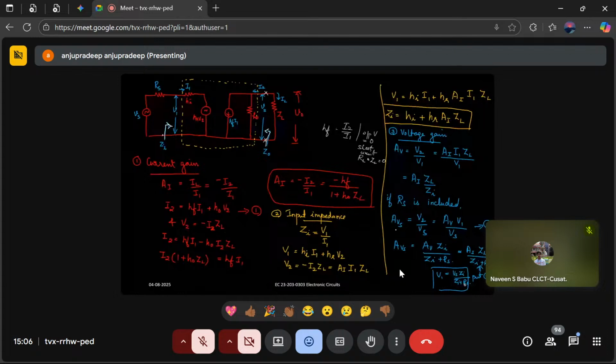Because once you get a circuit, what we will do is from the function generator, you select some voltage, say 40 millivolt. The function generator will be showing 40 millivolt, and then you will try to find the voltage developed across the load resistance RL. So the user will know only that much. We are assuming that the circuit is inside a black box. You don't know. So you are giving some input and you are expecting some output at the other side.